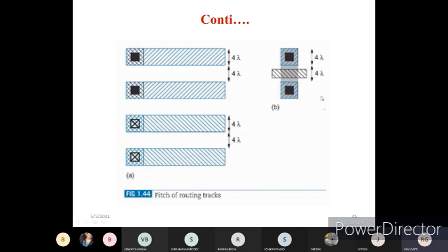And you can see here they have given you the transistor, that is an NMOS transistor. For this NMOS transistor they have given you two contact cuts. One is for the source and drain, meaning it has been connected to some other part. The distance between the polysilicon and the contact cut, meaning the width of this contact cut, is nothing but 4 lambda, whereas the polysilicon area between two contact cuts has to be a minimum of 4 lambda.